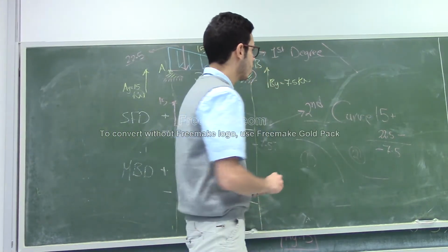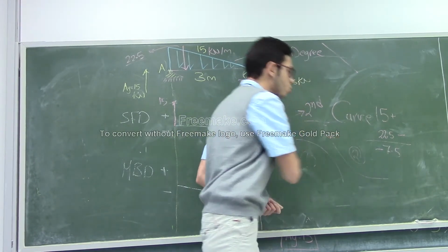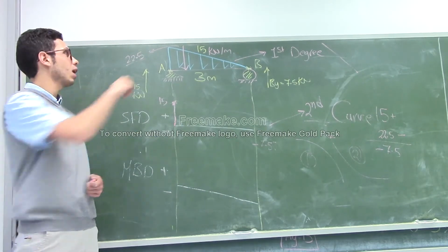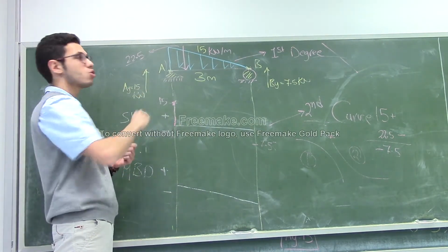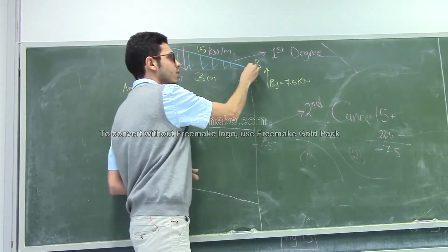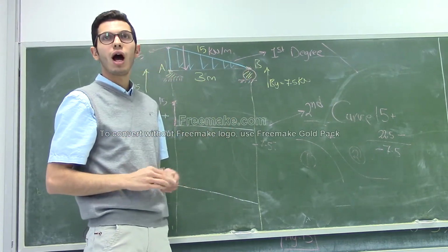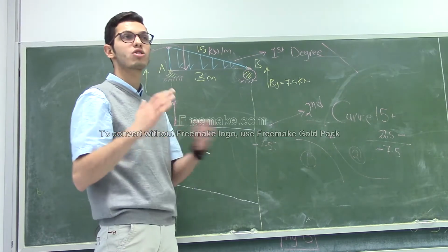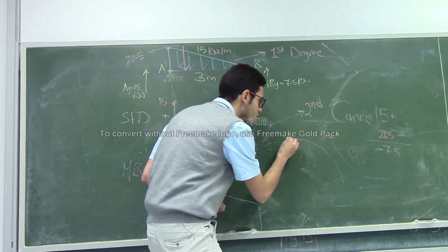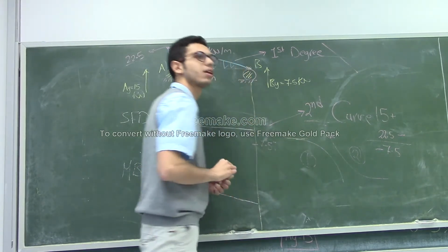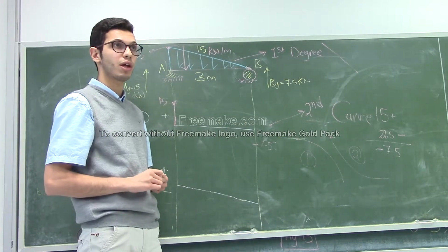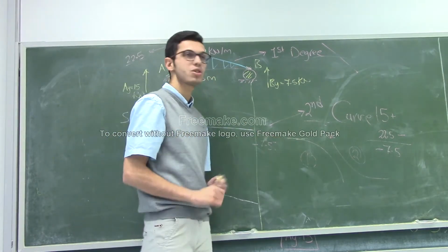As our friend Abdel Hadi says, we should choose this one. Why? Because here in the shear diagram, we start with a value, and here we start with a value, right? So this triangle is starting with a value, and at the end should be equal to 0. How can we discover that? By the slope definition, right? The slope here for this curve is horizontal. What is the meaning of the horizontal slope? 0. I told you that before. The meaning of the horizontal slope is 0.